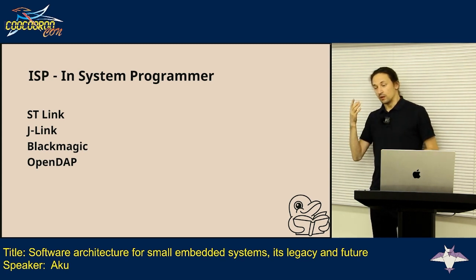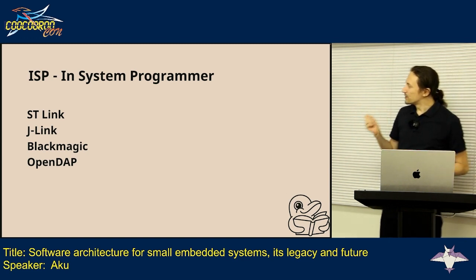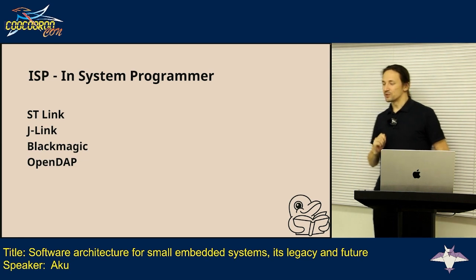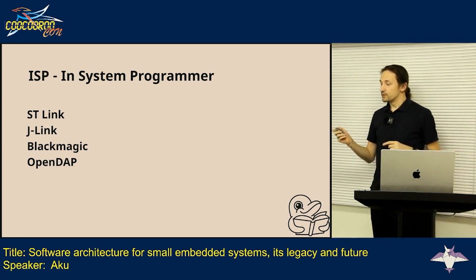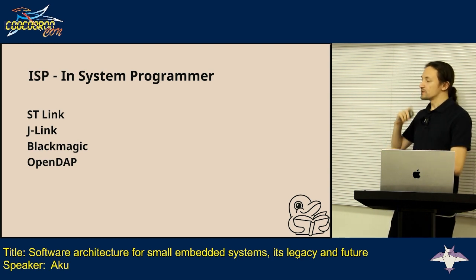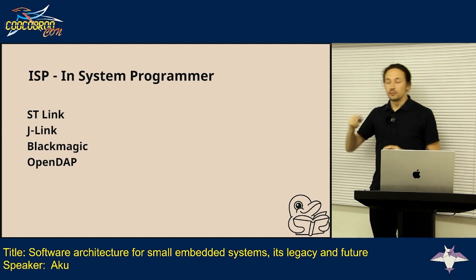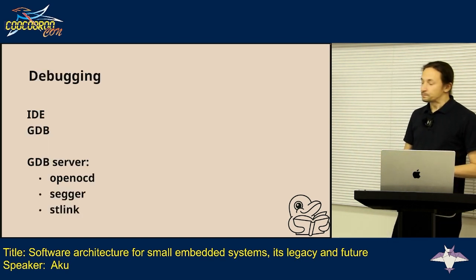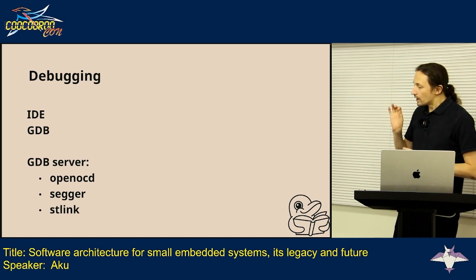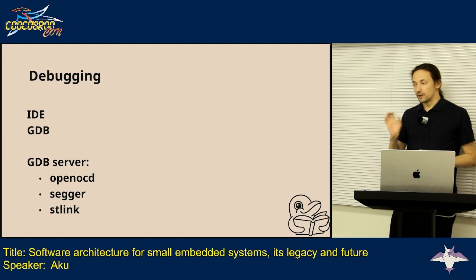So you can write software without thinking about where I should find a debugger, what kind of debugger will work with this board. Anyway, this debugger you connect to your PC, and then with special software you can just upload your ELF into the microcontroller that you would like to program. And when your software is already running on the MCU, you would like to debug it.